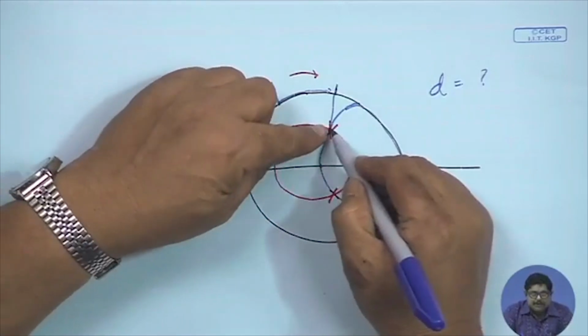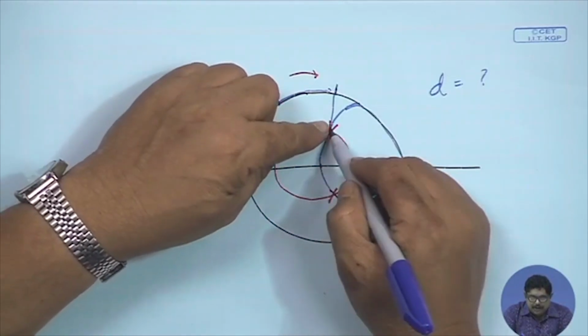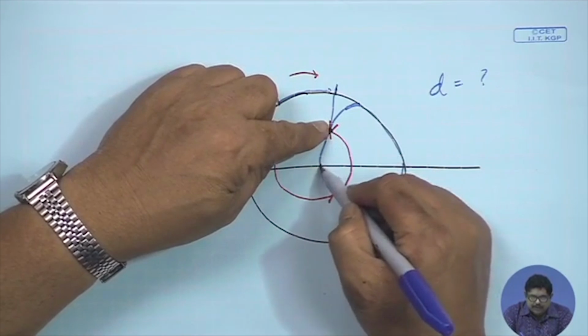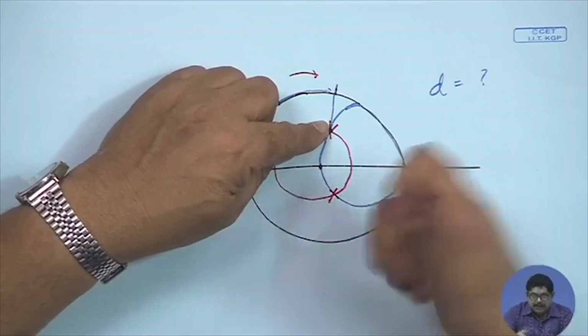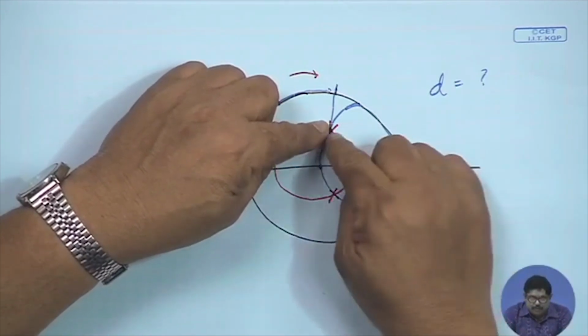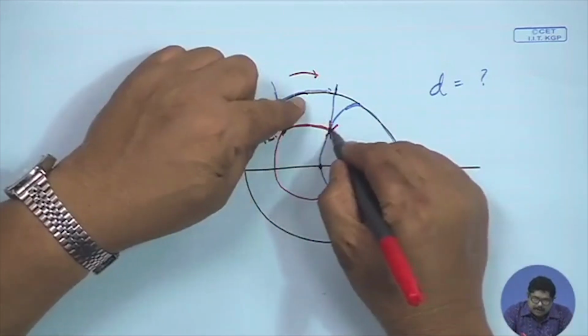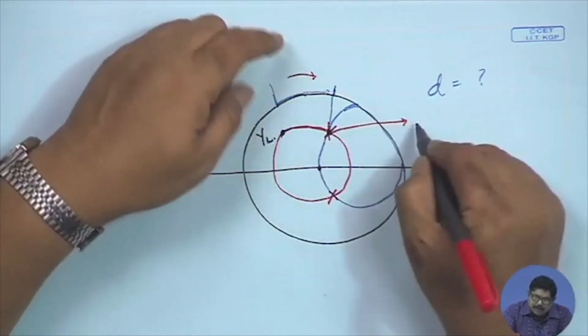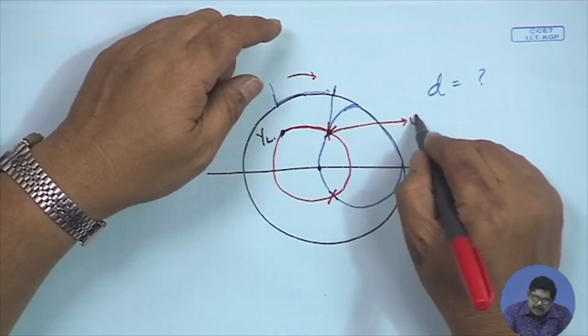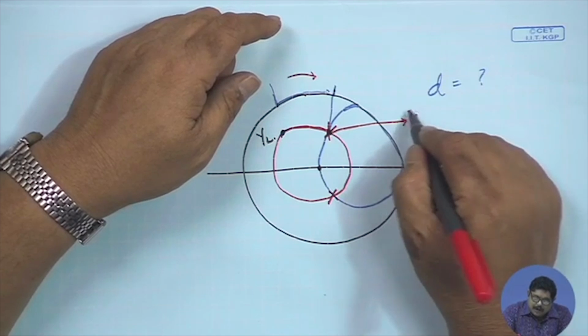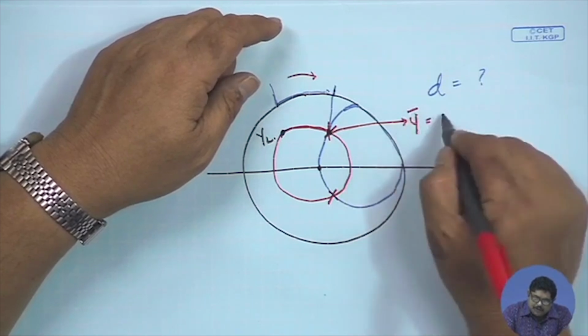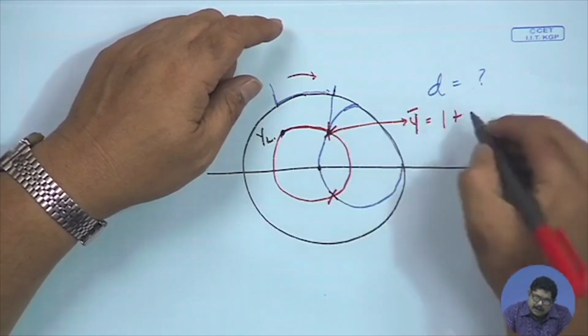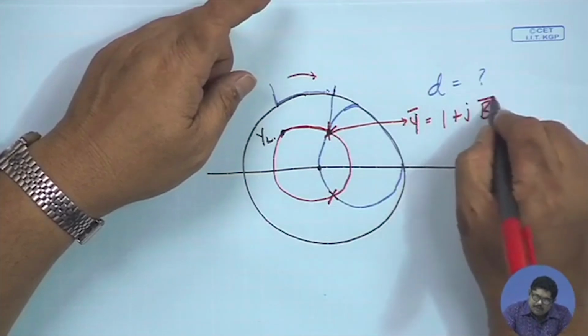Now, after coming here you know that you will have to come to the center of the chart to match it, that is done by the susceptance. So, from here you find out what the value of this point is. Obviously, it is the admittance seen here, that will be 1 plus some jB value.